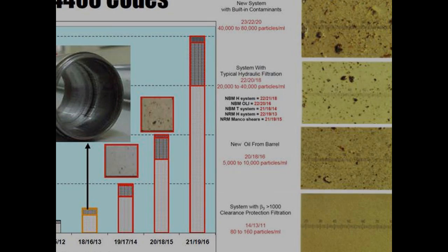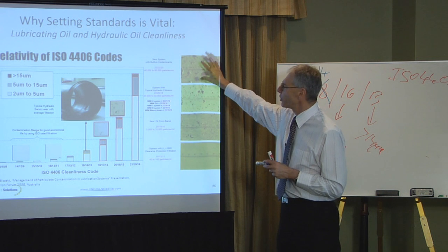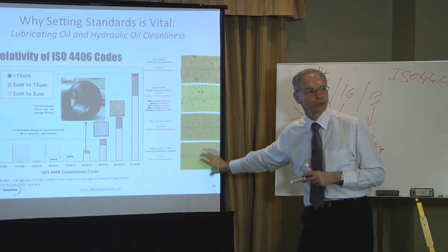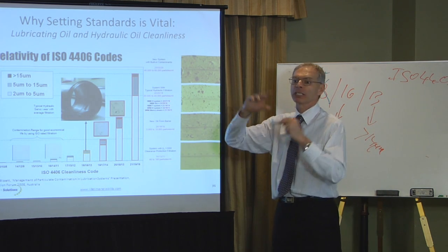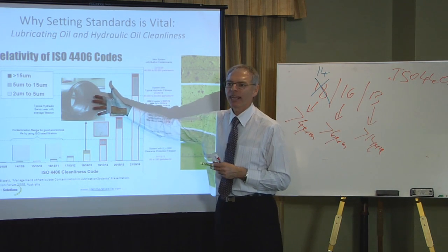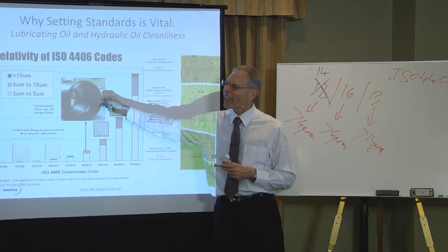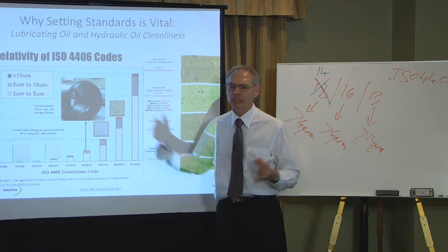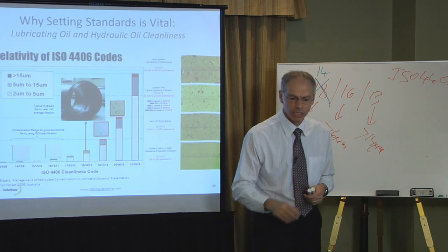So this here is, each of these black dots is an opportunity for a failure. So high opportunity of failure here, high risk here at this level. Here, low risk, because there's not much opportunity for failure. Not one, not zero, they're still in there. But because they're so dispersed now across a large amount of oil, the chance that that will jam up in here in enough numbers to actually cause this to seize, very unlikely. Whereas here, there's enough numbers to cause it to seize. And eventually, every now and again, the dice roll and come up the wrong number and the machine goes down.